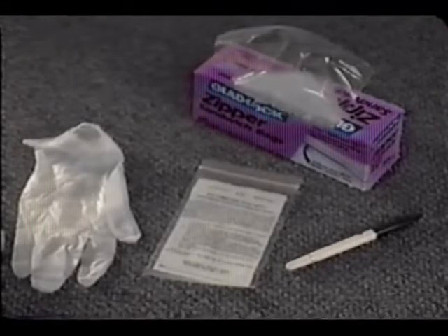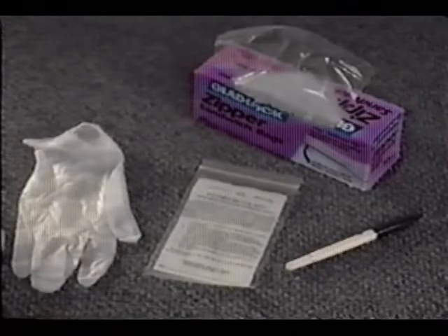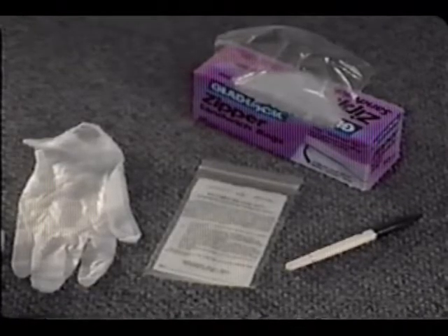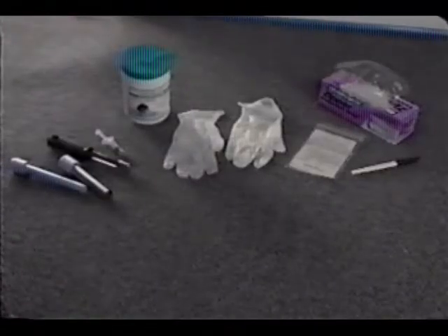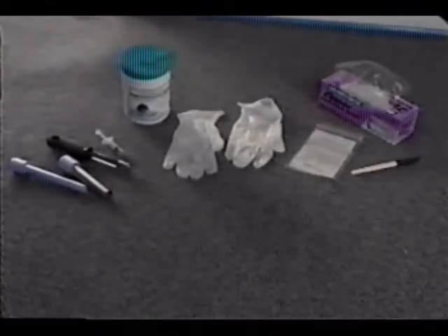Before collecting soil samples, prepare a property sketch showing the lot boundaries and the rough position of the buildings. This sketch will be used to record the sampling locations. In most situations, 2 composite samples per dwelling will be adequate. One from a play area, the other from around the building foundation.